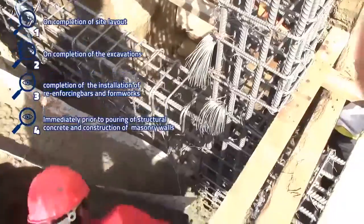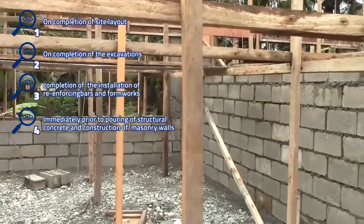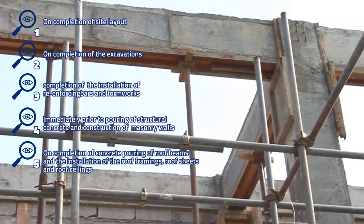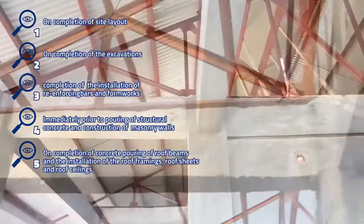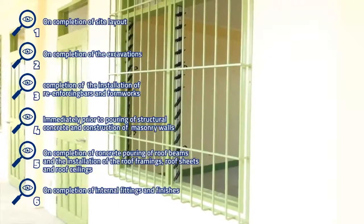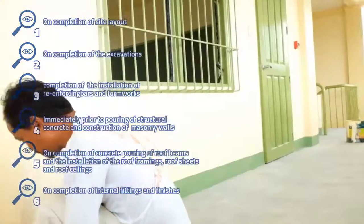Key inspection point 4. Immediately prior to the pouring of structural concrete and construction of masonry walls. Key inspection point 5. On completion of concrete pouring of roof beams and the installation of the roof framings, roof sheets, and roof ceilings. Key inspection point 6. On completion of internal fittings and finishes, doors, windows, plumbing, and electrical works, including painting.